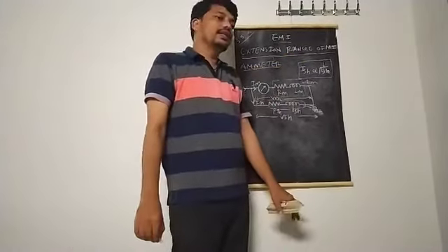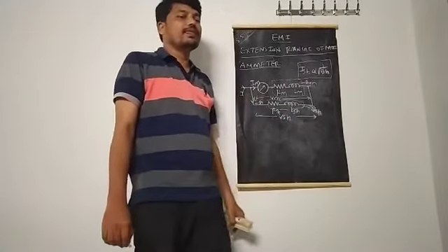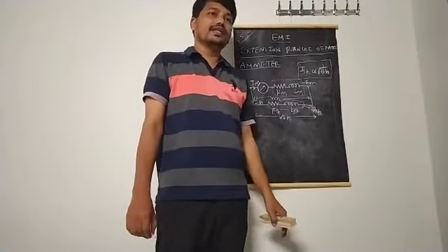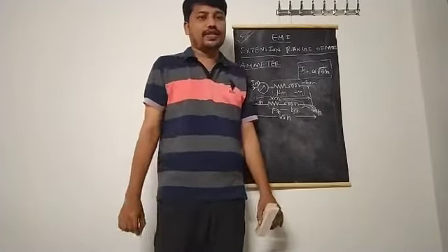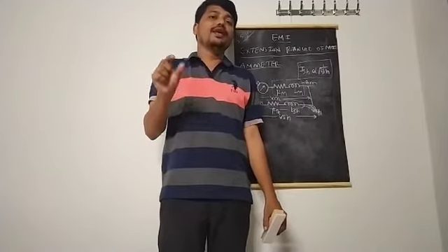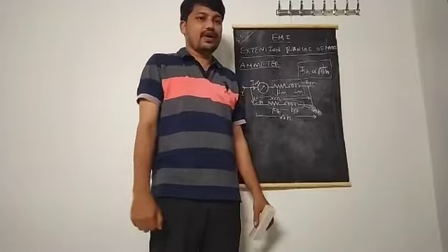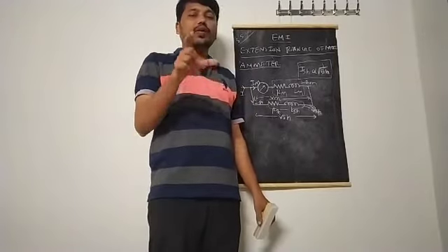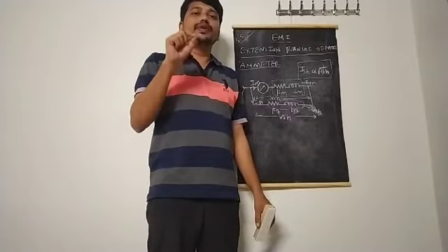In general, we know the advantage of the moving iron instrument compared to PMC. PMC can measure only DC. That means the permanent magnet moving coil instrument can measure only the average value of DC, but it can't measure AC values. Therefore, in the equivalent circuit of the meter, we do not consider any inductance effect in the PMC instrument.